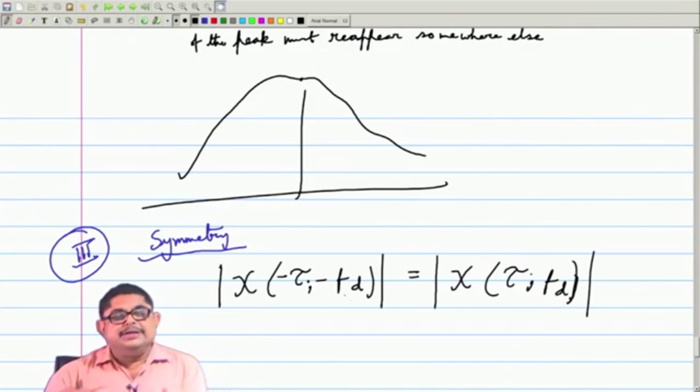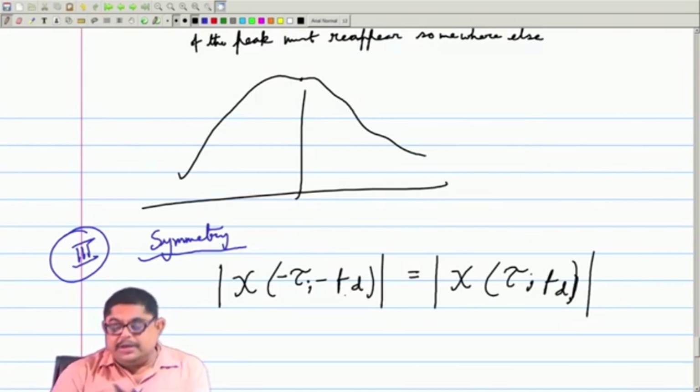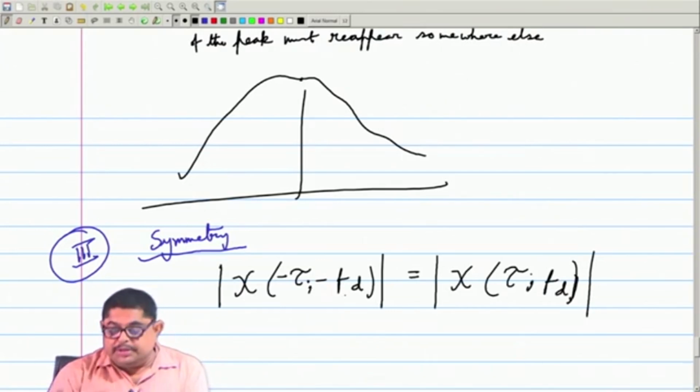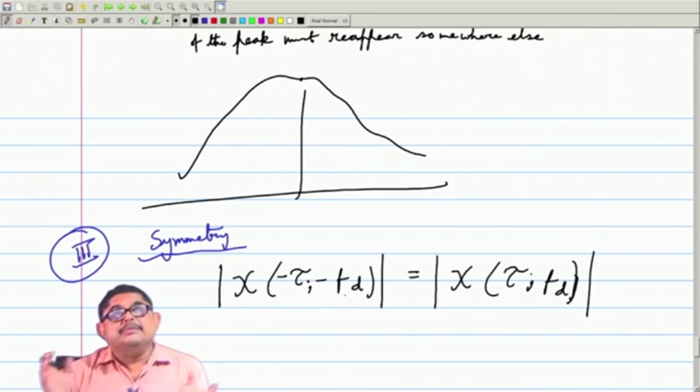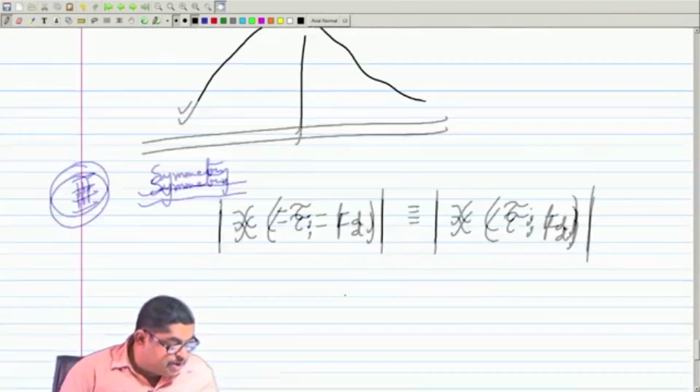It says that it is sufficient to analyze only two adjacent quadrants of the ambiguity function, generally the first and second quadrants. That means if you find the positive Dopplers, the other you can always show from symmetry. As we have done in our derivation of the ambiguity function of the chirp signal, we did all possible cases, but actually using symmetry, knowing one you can tell the other.